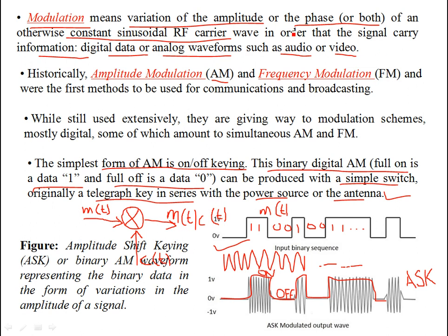So in the continuous schemes like amplitude and frequency modulation schemes, you don't have finite modulation states. You have a continuum of variation in amplitude or frequency with respect to the audio or the message signal. So, for example, if it is a continuous AM or a continuous FM, the amplitude, or frequency in case of FM, is being varied with respect to the amplitude of the audio or the message signal. So there's a difference in digital and analog modulation schemes.